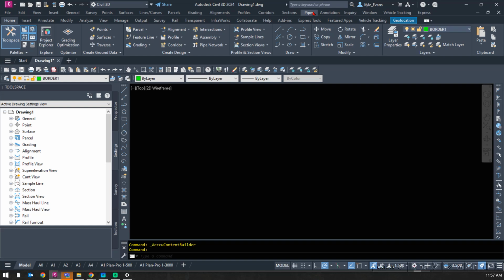With terms of a manhole, we have bottom thicknesses, we have wall thicknesses, we have the cone height at the top. So a manhole is just not a straight tube. It has a cone at the top with a 600 millimeter or something manhole lid cover.